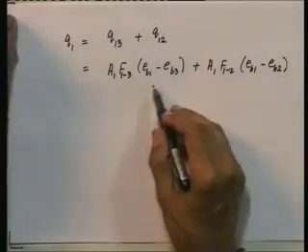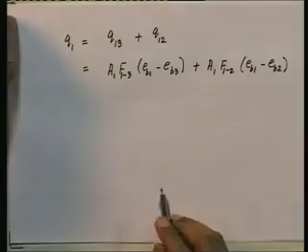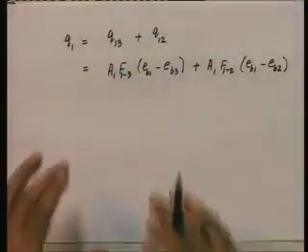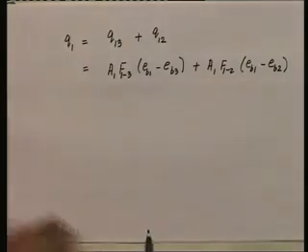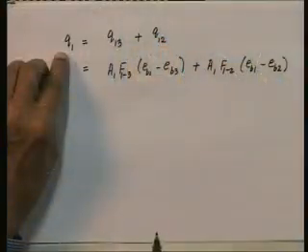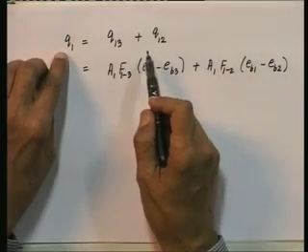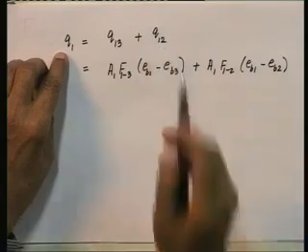I am writing EB1, EB2 and EB3 instead of writing everywhere sigma T1 to the power of 4 or sigma T2 to the power of 4 or sigma T3 to the power of 4. That is really what EB1, EB2 and EB3 represent. Instead of keeping on writing the bigger expression, I will write EB1, EB2, EB3. At the end, I will substitute the Stefan-Boltzmann law. All right. So, the rate at which I supply heat at surface 1 must be equal to the heat exchange rate between 1 and 3 and the heat exchange rate between 1 and 2.